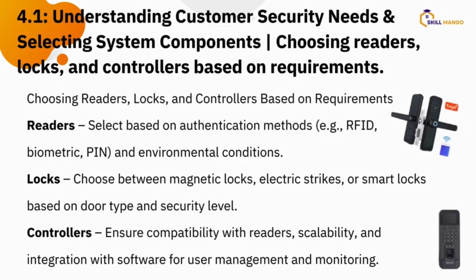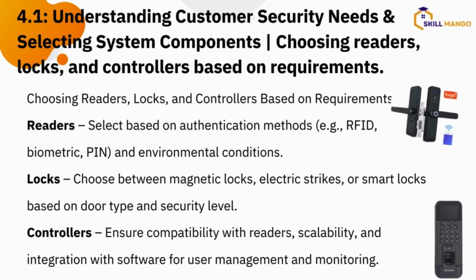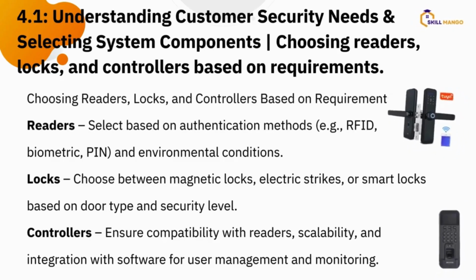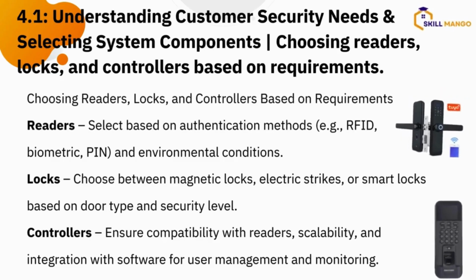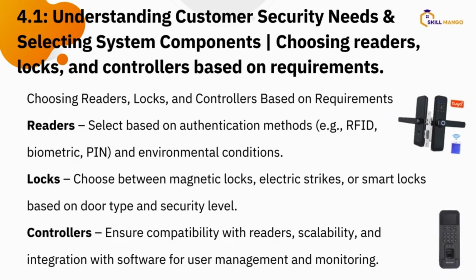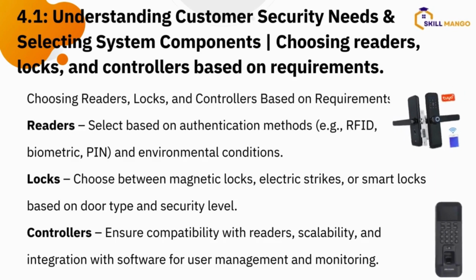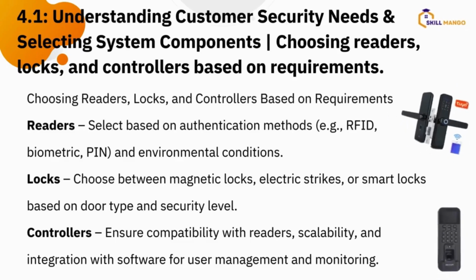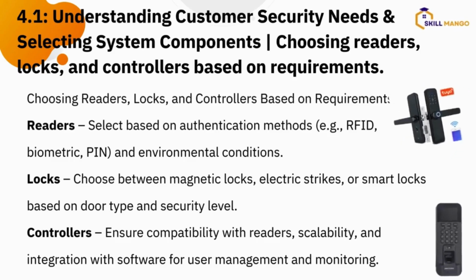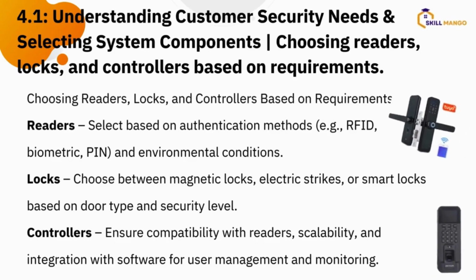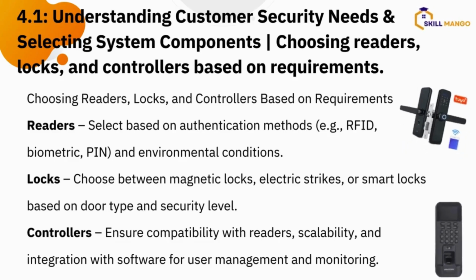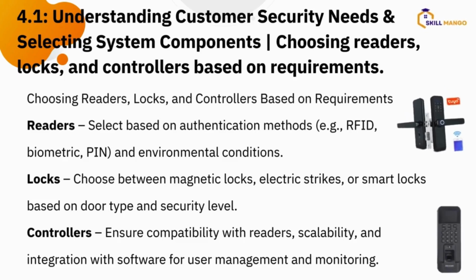So in my own opinion, I would go with the mag lock because with a mag lock, in case of emergency or power outage, everywhere opens. So you know that people can go in and out. But for the electric strike, it stays locked until you get somebody that has access or you get the exit button to disengage. All right. Then if there is a power outage, it stays locked until they bring in the power or you power the backup or the backup system is working.